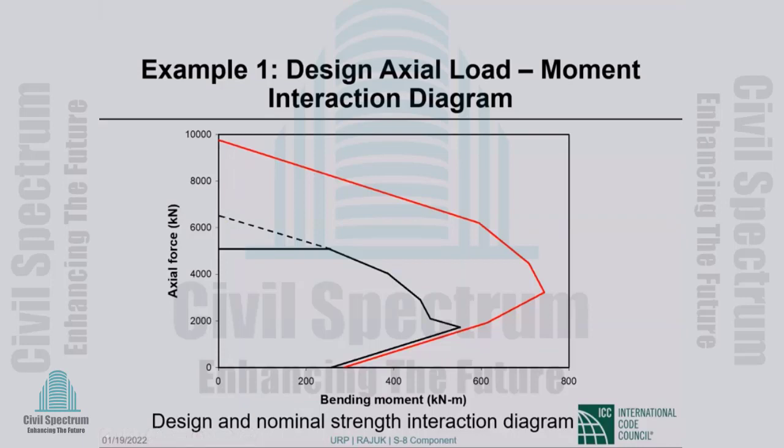So these very important load moment interaction diagrams are constructed using computer programs that are available. Almost nobody will do it by hand, but the exercise that we went through, I think, is extremely valuable. You see the neutral axis depth shifting. You see how the numbers are changing. If I had more time, I would probably stress how the axial loads and moments are changing. Okay, very nice to see.